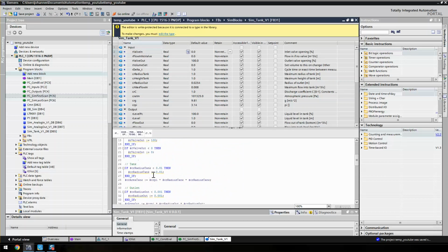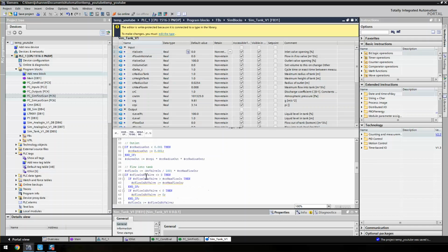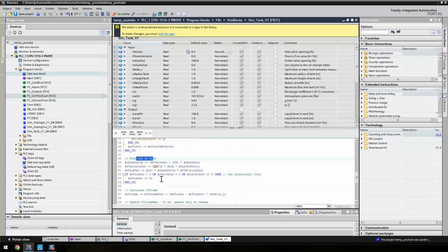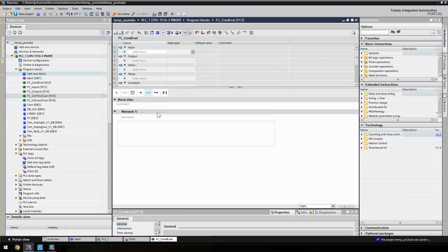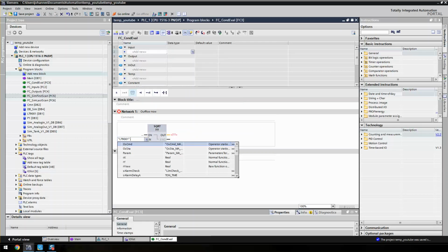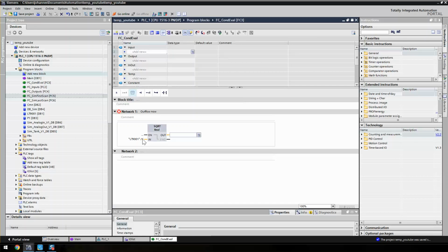We already know it pretty well. Let's see here: flow into tank, flow out of tank, square root, some gravitational acceleration, all the good stuff, and the area of the valve and a loss coefficient. We'll dumb that down to something useful and call this net outflow now. The outflow now will be the square root of something, specifically our height.